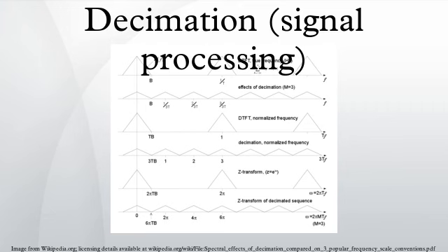The bottom pair of graphs represent the Z transforms of the original sequence and the decimated sequence, constrained to values of the complex variable z of a particular form, and then the transform of the x[n] sequence has the form of a Fourier series. By comparison with the earlier equation, we deduce the result, which is depicted by the fifth graph in Fig. 1. Similarly, the sixth graph depicts the decimated case.